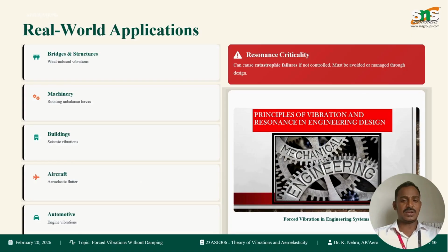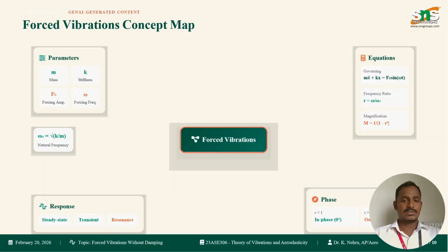Coming to real-world applications: in bridges, wind can cause oscillation. In machinery, rotating imbalance creates periodic forces. In buildings, earthquakes induce vibration, and especially in aerospace, the concept is directly linked to flutter, which can destroy aircraft structures. Avoiding resonance is a key design requirement.